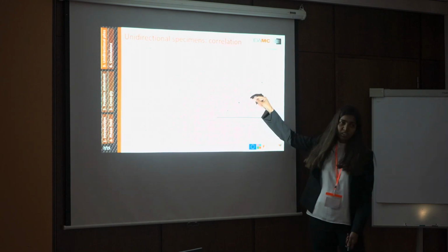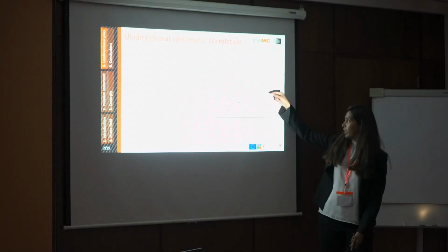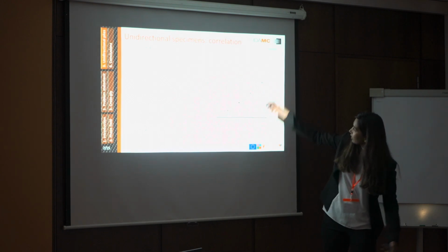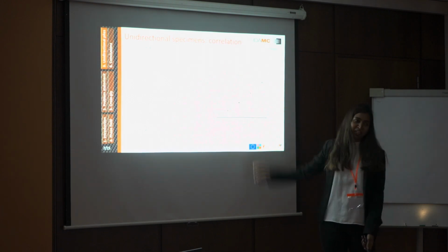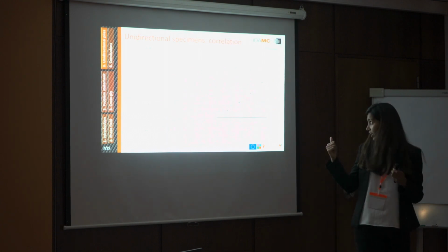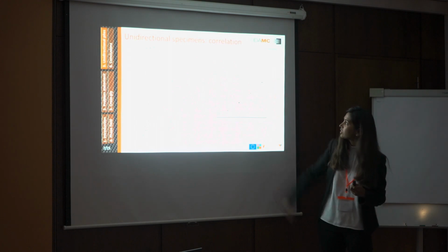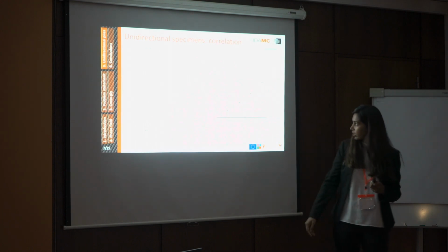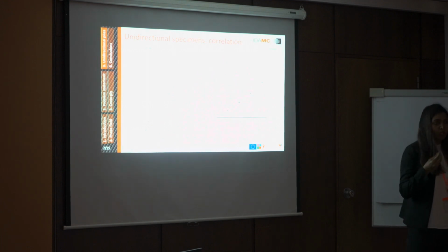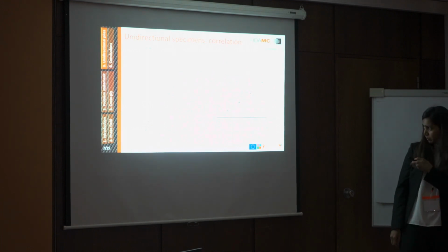So here the solid circles represent the moment values obtained from the numerical simulations, and the dotted lines, which is not clear here, are from the experiment. We tested 4 samples for each thickness in our experiments. That's why we have these 4 dotted circles. We can see that they match perfectly well, which validates the usage of cohesive elements to model the interlaminar delaminations.